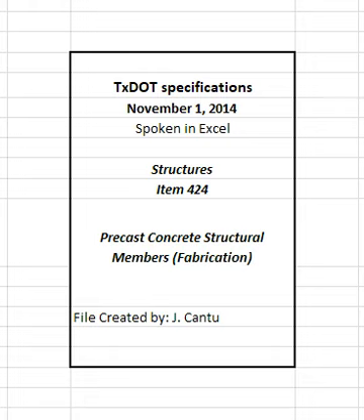4.3 Workmanship. Formed surfaces must not have excessive surface honeycombing, aggregate or mortar pockets, air voids, lift lines, stains, or vibrator marks. Remove form joint offset marks in excess of the tolerances specified in Section 424.4.2.1.1, External forms, and fins and rough edges along chamfer lines, in a manner that will not damage the member. Repair fabrication holes, except box beam and U-beam drain holes, with an approved repair material and procedure. Recess strands in accordance with the concrete repair manual unless otherwise shown on the plans.